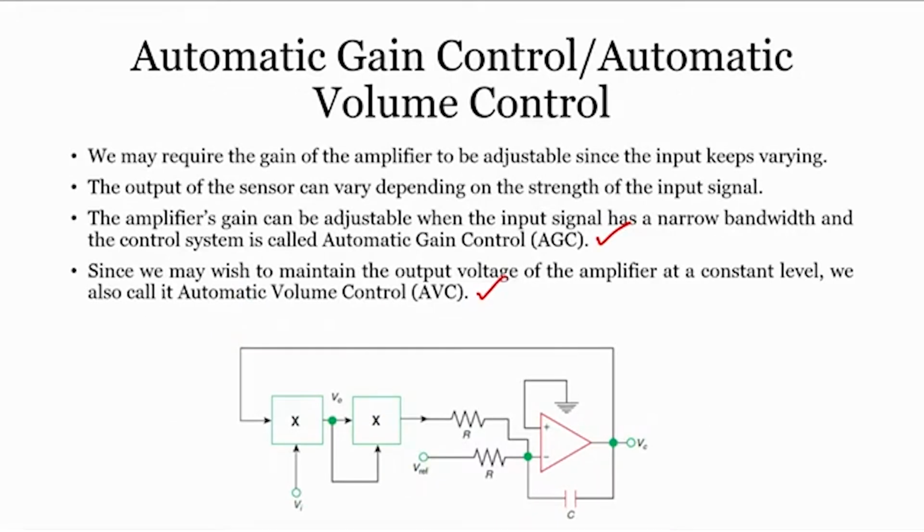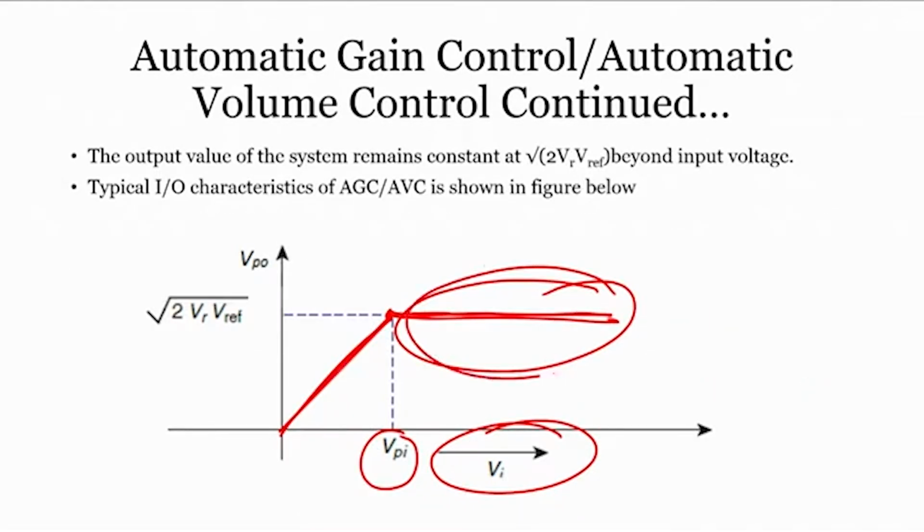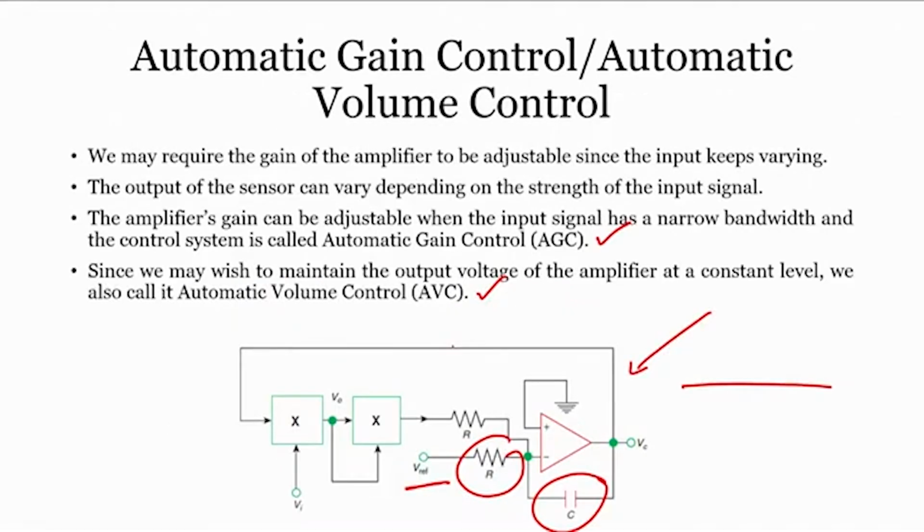For that we need to use this circuit, and in this circuit there is a reference voltage. The input voltage is a sine wave, which is multiplied once again, becoming sine square. When you have a sine square, it is like ripples, or a full wave rectifier kind of signal. Since there is an integrator here, R and C forming an integrator, the output will be almost constant. That is what we see here, and the output is constant. So, using this circuit we can control the output voltage.